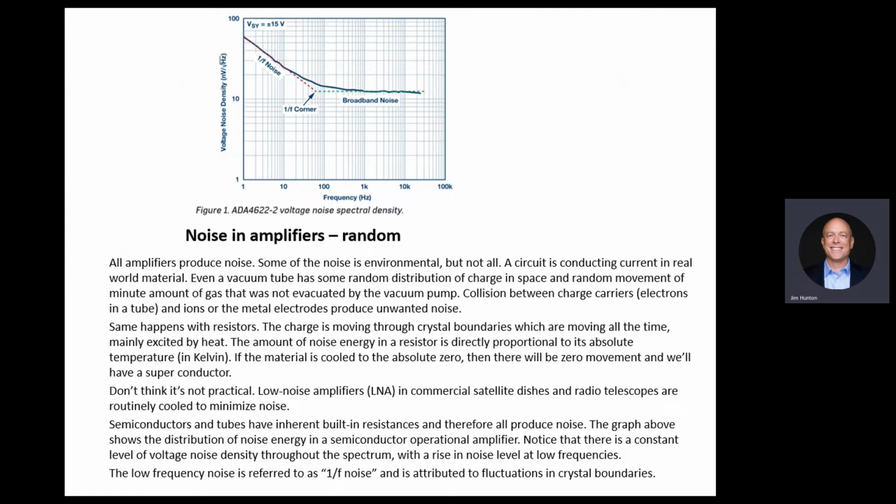It's a phenomenon that's actually random, but it exists in many things in life in general, that at lower frequencies there is more randomness. In this case, we think crystal structures behave differently and give you more noise. So you'll see devices like JFETs, look at the characteristic curves, how the noise is shaped. Some of them have very low 1/f noise, some of them don't.